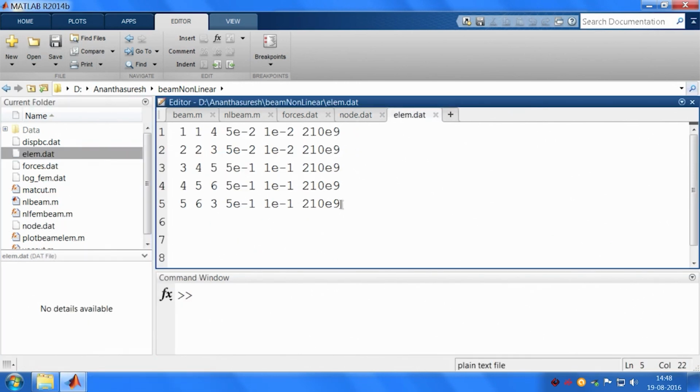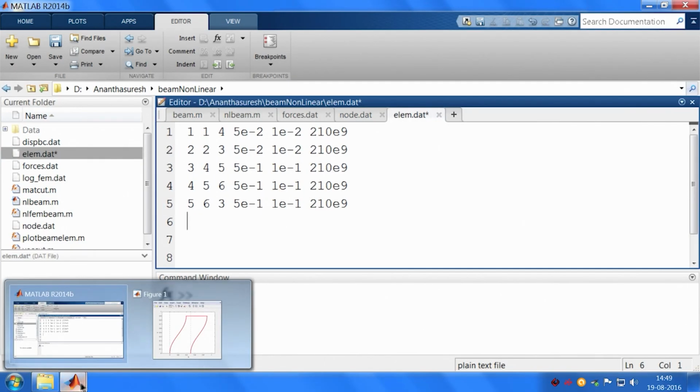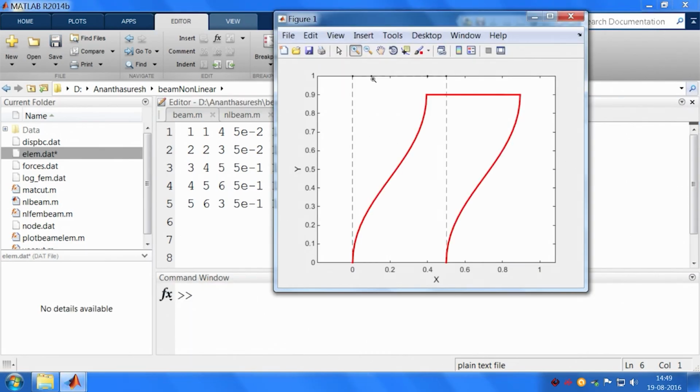So here we already have 5 elements. Now I want to add 2 elastic segments and 2 rigid segments. So 2 elastic segments, again if you go back to the figure, I have to hang from that node to this node that I have created, and then that node to this node I have created. In between I have 2 more, that is from here to the center of gravity to the other one of the element.